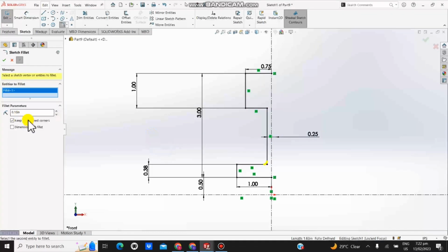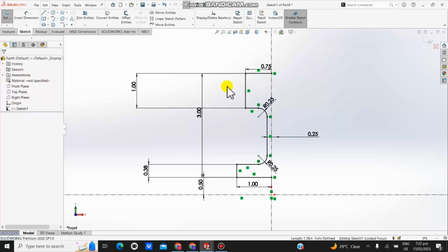And what's within my dimension here, which is from the question, is 0.25. Then press enter. Check it. Do the same thing for the other side. Click this line, click this one, 0.25. Check it. So I am almost done. Then I mark it. So now there is a hole at this part, so I have to work on that hole. So let me zoom to that part.